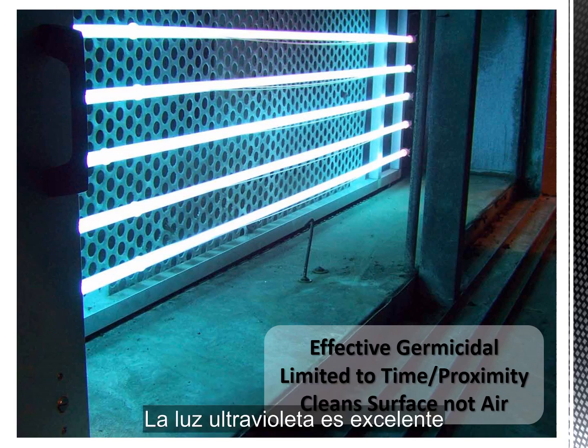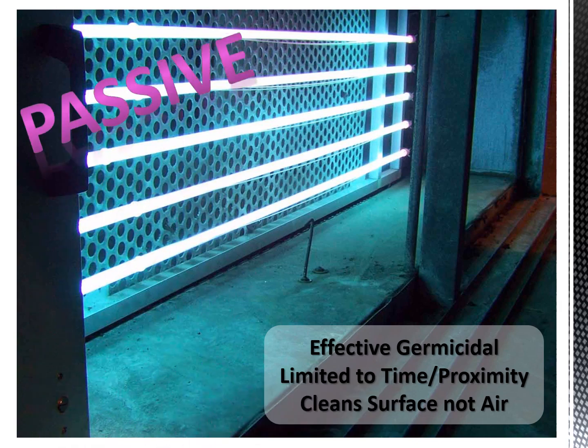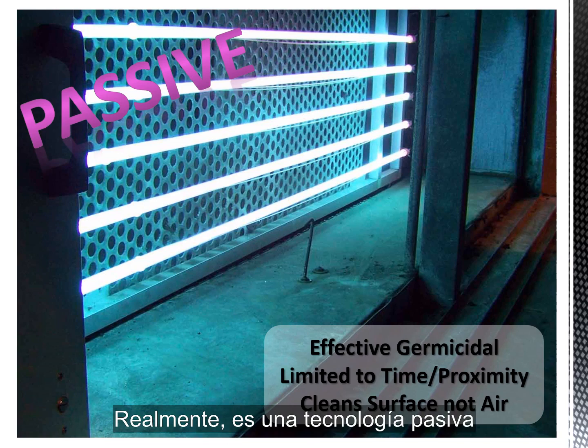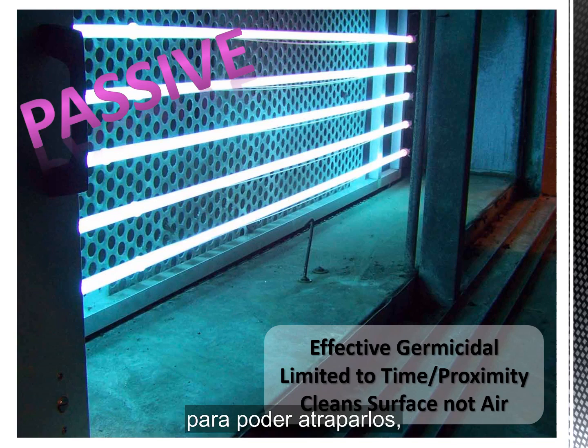Ultraviolet light is great for the surfaces inside the system, but not very effective in the airstream. It really is a passive technology, waiting for the bugs to come close to it so it can zap them, change their DNA, or neutralize them.